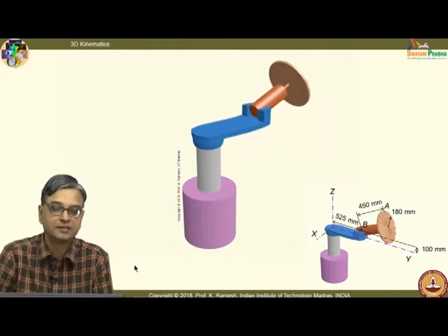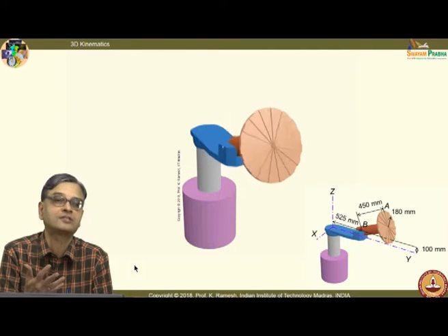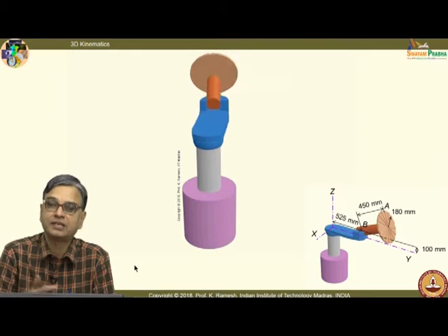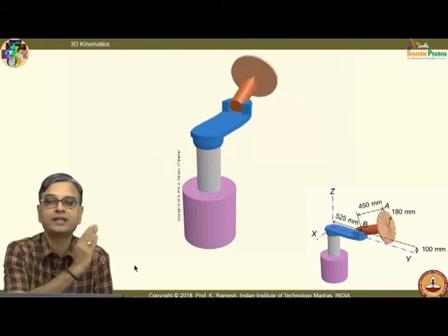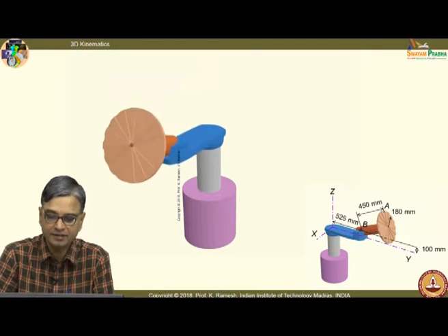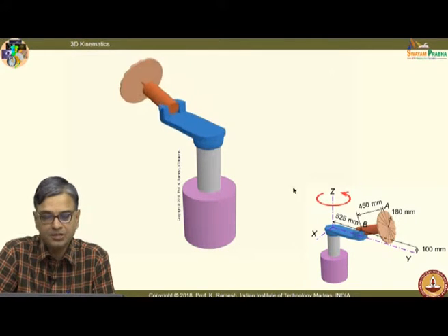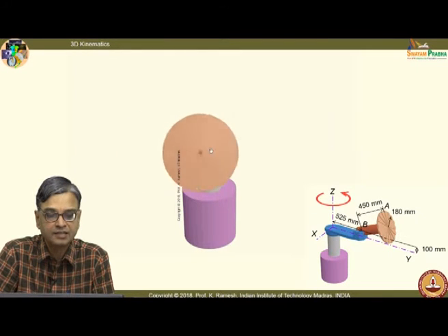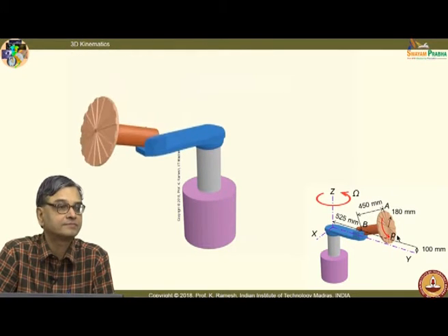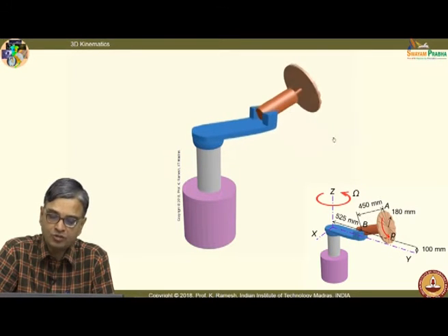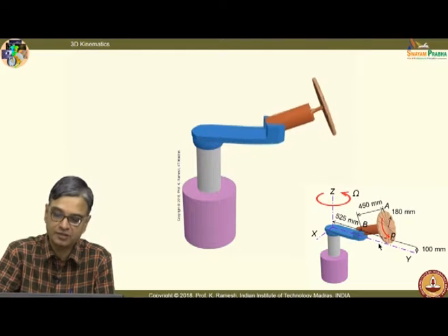So, let us solve some interesting problems and just observe the animation, so that you recognize what are all the motions that are available to the mechanism. So, you perceive and write them clearly in the sketch. One is, I can see that it is rotating about this vertical axis, that is very clear. So, I have a rotation about the z axis. Then observe that this disc is not stationary, this is rotating anticlockwise, that is also very clear. And you know, this also has a provision, this motor can be kept at any angle. There is also a provision like this for this,